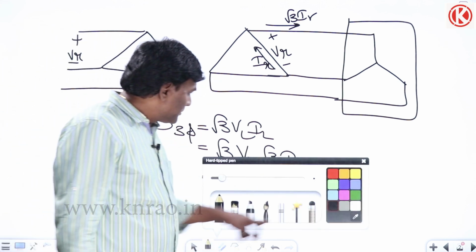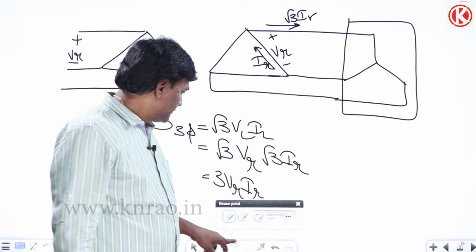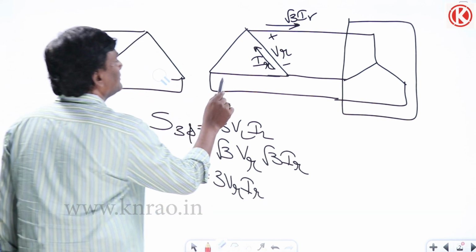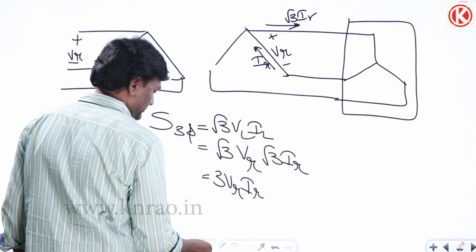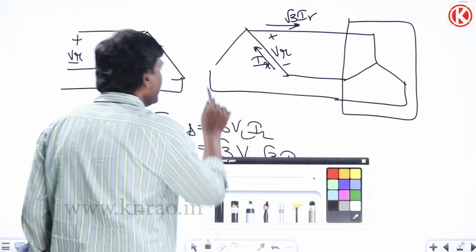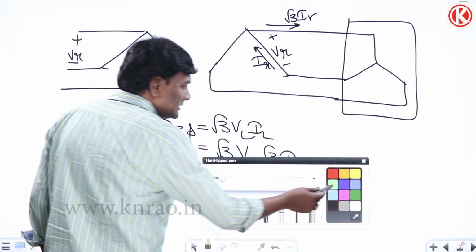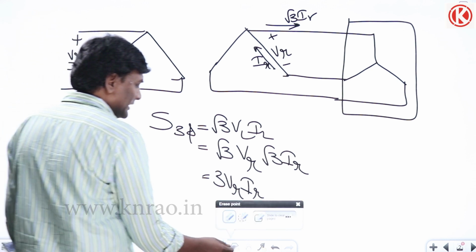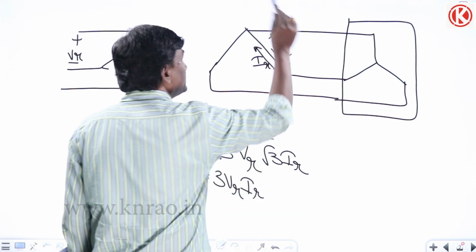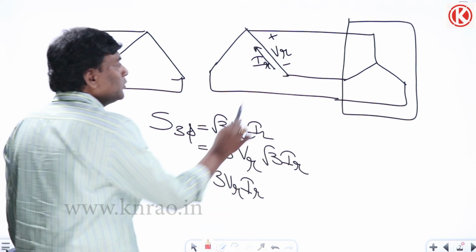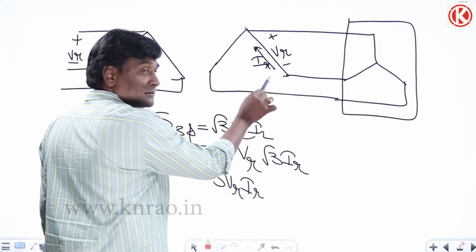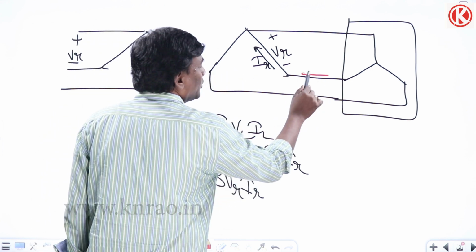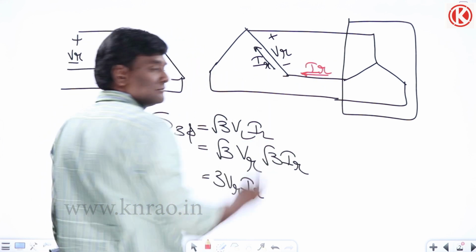Now for example, let me remove this particular winding. If I remove this winding, voltages will be the same. But if you think of currents, if the phase winding copper is being utilized at rated current, how much will be the current here? Rated current.